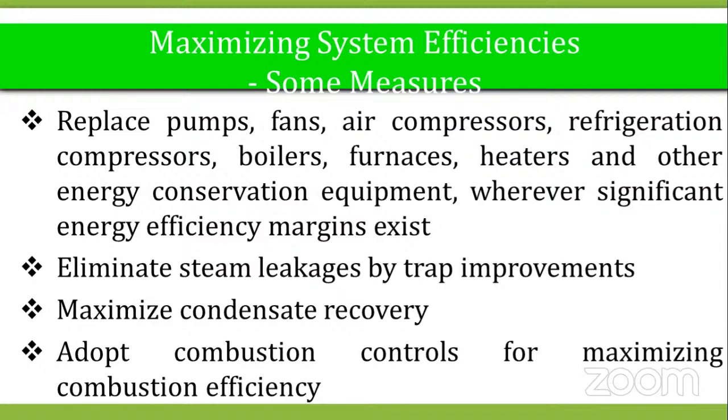We need to understand the improvement methodologies to work on it. And the condensate recovery, it is something like we have a lot of condensate. So wherever we are going to lose the heat, the heat circuit is the main thing for boilers. We may intentionally cool it for some purpose. For example, a hot well is an area where the condensate needs to be. How well the condensate is working, how much heat is being lost, what is the specific heat that is lost, or latent heat governed by the heat cycle. All of this needs to be understood, and we need to work on maximizing the condensate recovery.